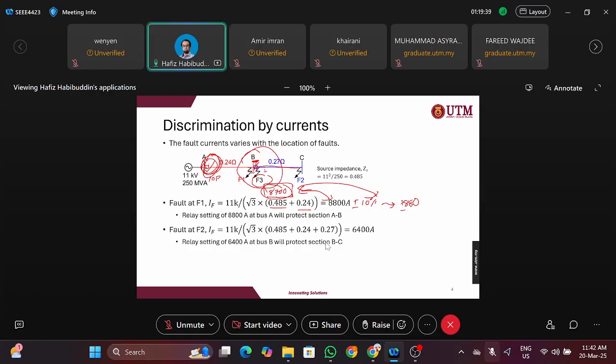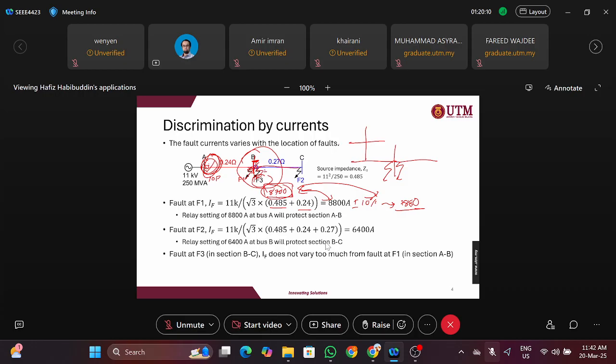So we are tricked here. The problem is you cannot distinguish faults at these two locations. Essentially, it is effectively the same point, two different sides of the bus bar, sorry, the conductor here. You have a fault here, you have a fault here, different side only. So it is not very practical to distinguish those faults. So again, you're screwed here. Not so good.